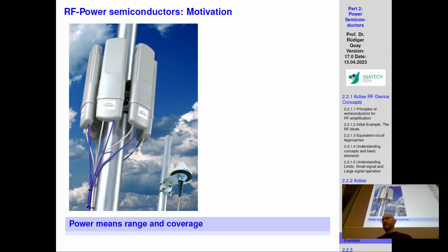You need raw bandwidth, and in order to increase that raw bandwidth, every time you hear new 4G, 5G, 6G, 7G, whatever the Gs will come, it will always be some higher frequency point where larger bandwidth is covered. And they are moving higher at higher frequencies. You know all the amplifier curves, the FT and Fmax, as we discussed last time, the maximum current gain FT and the maximum unilateral gain of Fmax, maximum power gain, they all tend to go downwards with their increasing frequency. And at some point you have them all at unity, which is you won't have any gain.